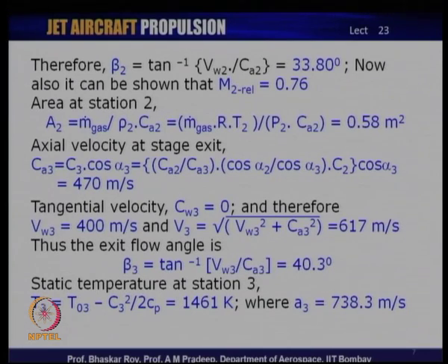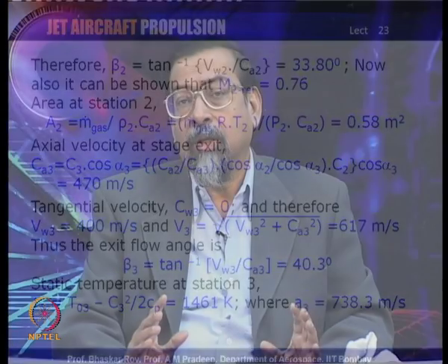And most of the present day designers are extremely sensitive to the efficiency of the turbines, and hence they try to keep the turbines subsonic even today. And the other thing is, a higher level of work done is being accomplished by increasing the turbine entry temperature, and this increase of turbine entry temperature is quite often the focus of attention of modern research, with more cooling technologies applied.